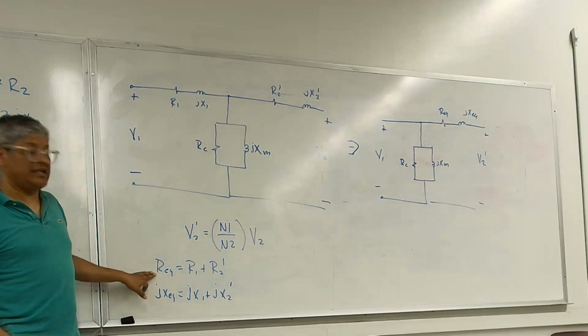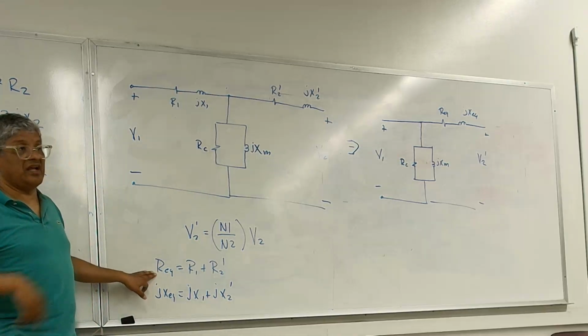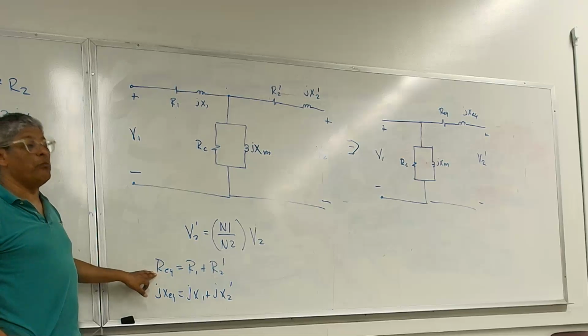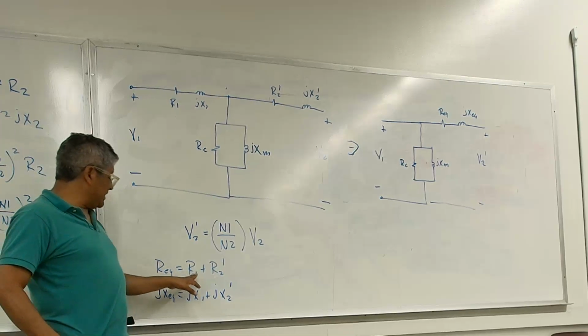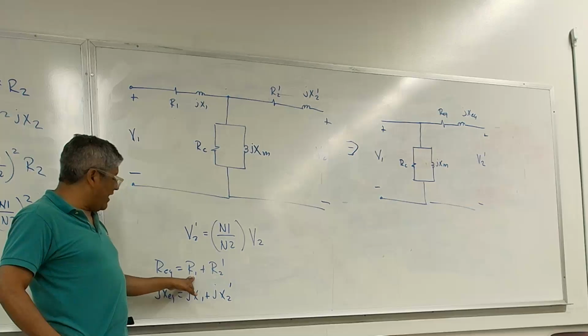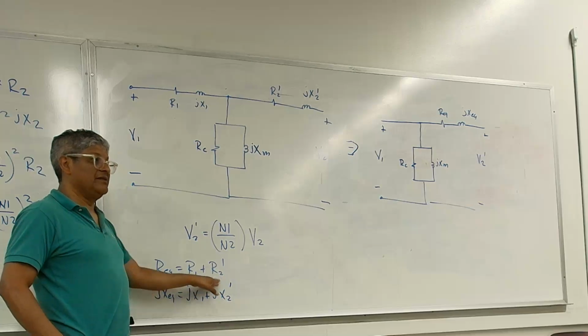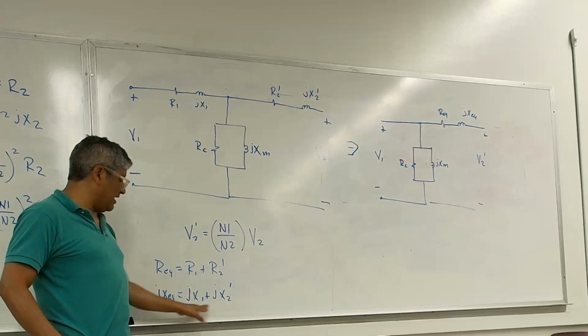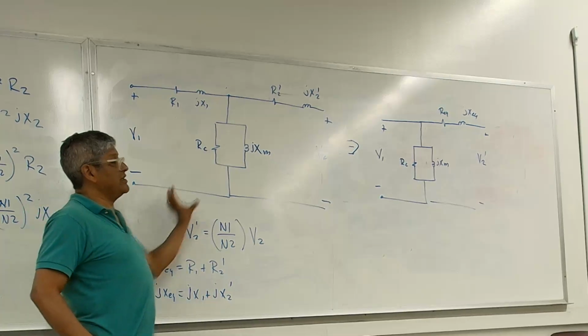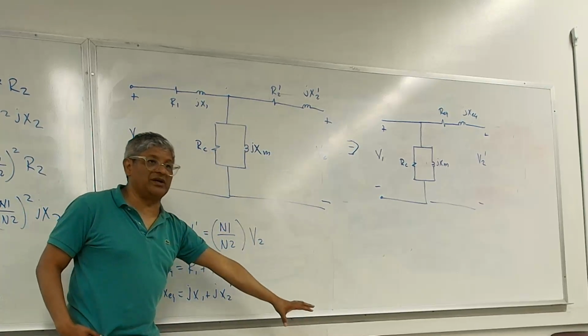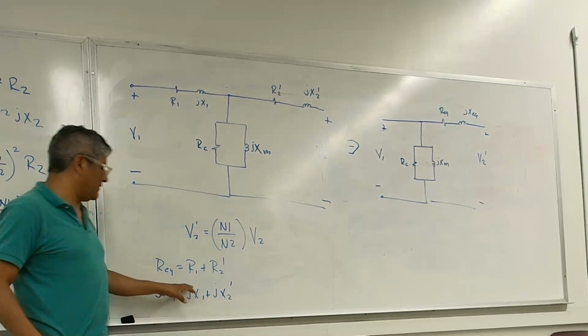Say, for instance, they tell you the equivalent resistance of that transformer is 10 ohms. You can say that then there's 5 and 5. You can split it half and half. Same here, half and half. Obviously you're going to have to transfer it to the secondary if you want a full-blown model, right? And we'll talk about that.